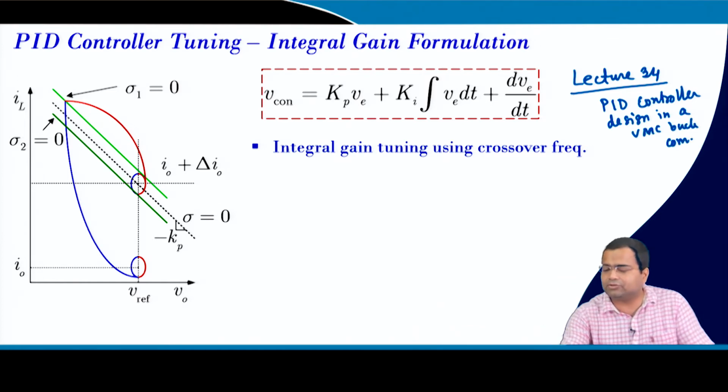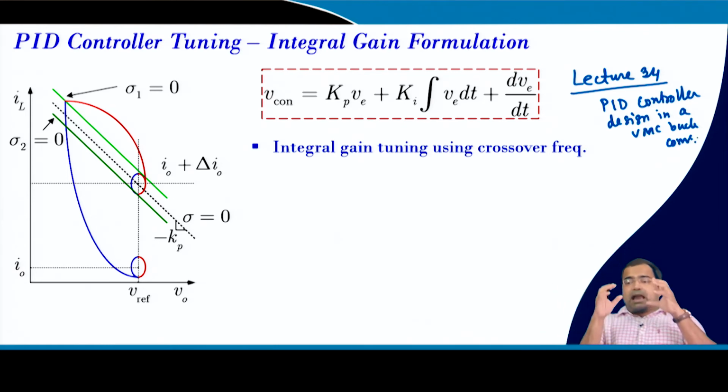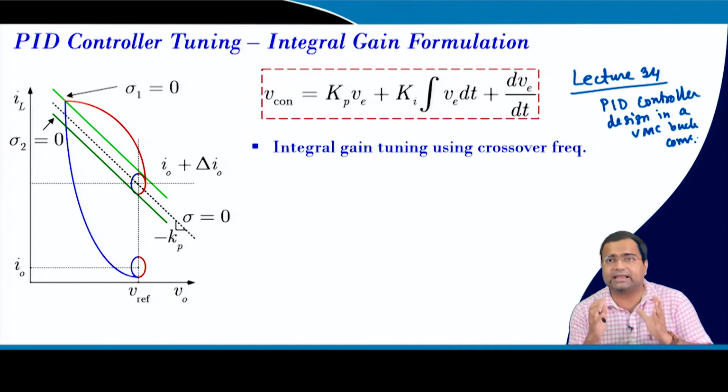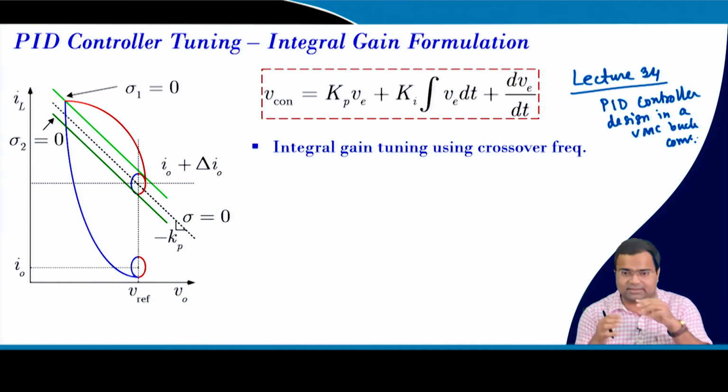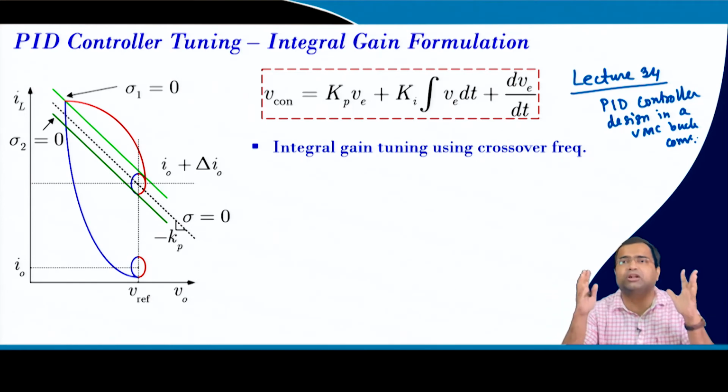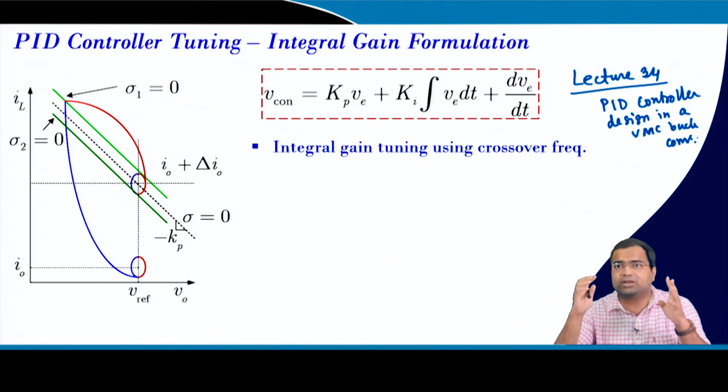So, that lecture talked about PID controller design, and there we found that if we use a PID controller, we can, by means of an analytical stable pole zero cancellation, get a first order closed loop equation. But unfortunately, we could not get suitable model matching even up to 1/10 of the switching frequency. Our model was limited. So, that is why we are considering this PID controller gain.